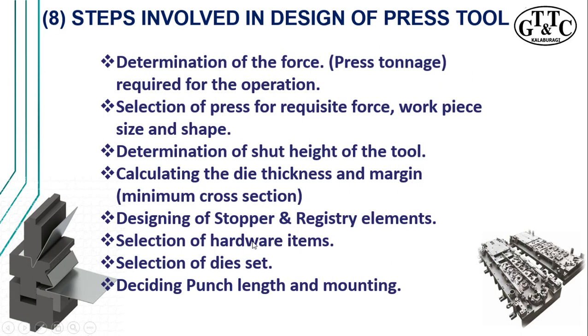It has to be finalized what actually is necessary, because once the type of tool has been finalized, then all these things come into the picture. And then selecting the right die set, whether you want a rear pillar die set or a center pillar, diagonal pillar, four pillar, or sometimes multi-pillar die sets as well. In case of a 16 stage progressive or more than 16-20 stage progressive, there will be more than four pillars in a particular press tool. So it can be a multi-pillar die set.